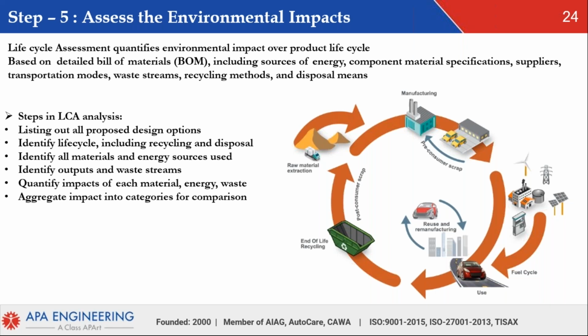The main steps involved in an LCA analysis are listing out all proposed design options for the product, identifying the complete product life cycle, including recycling and disposal, and identifying all the materials and energy sources used as input and all the outputs and waste streams. Once we have all the above listed information, the next step is to quantify environmental impacts based on identified inputs and outputs. And finally, aggregate the quantified impacts into categories for comparison.